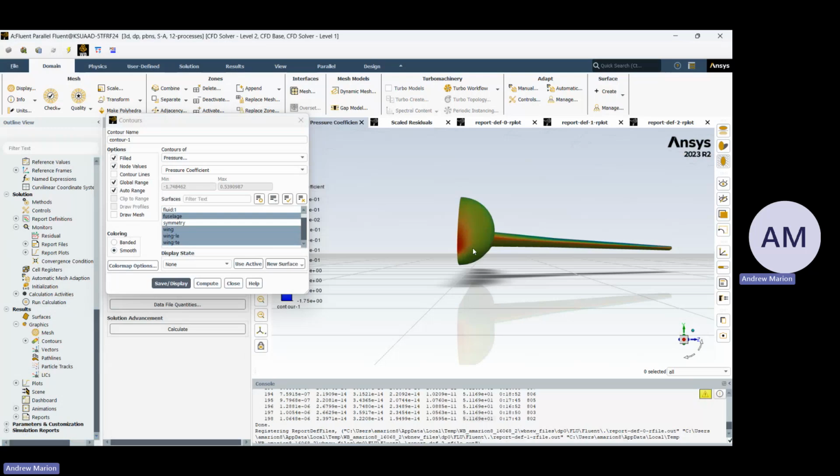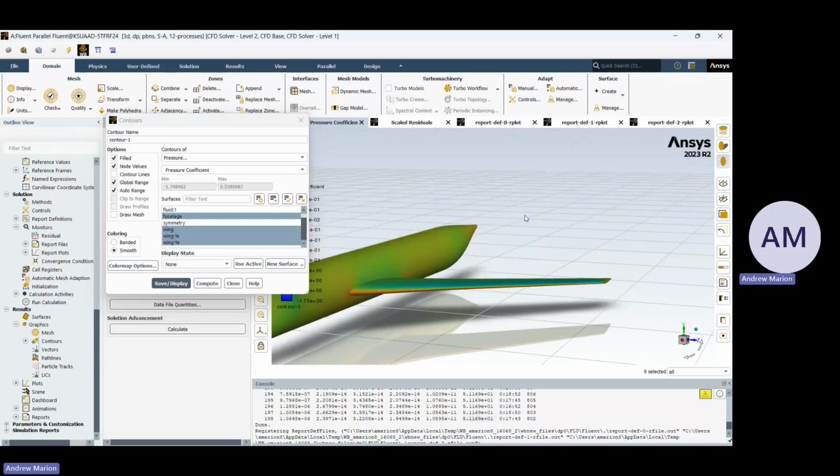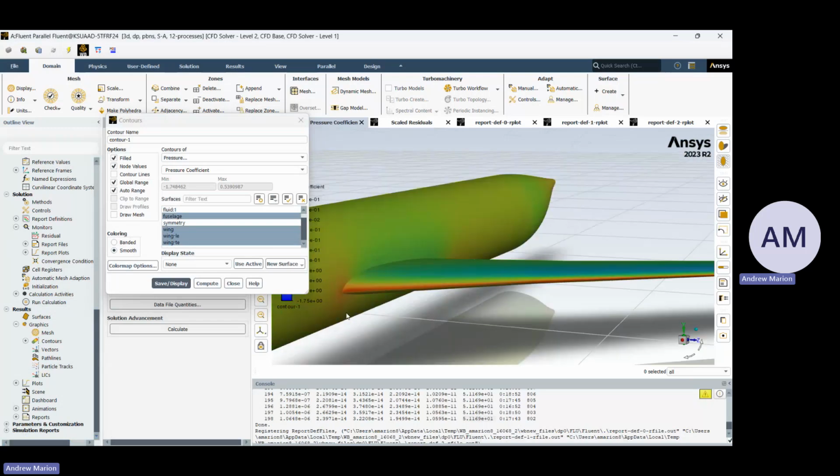All right. So if we take a view at the front of the aircraft, you can see there's a high pressure region at the nose, and that's where the air is coming in contact, because you have a large surface area. So that's going to add drag, but it's unavoidable because you obviously need surface on your aircraft for it to do something. But there are ways to minimize it: making the cross section smaller, making smoother edges, because you can see it also does it along the leading edge of the wing. You have this high pressure region, and that creates drag.